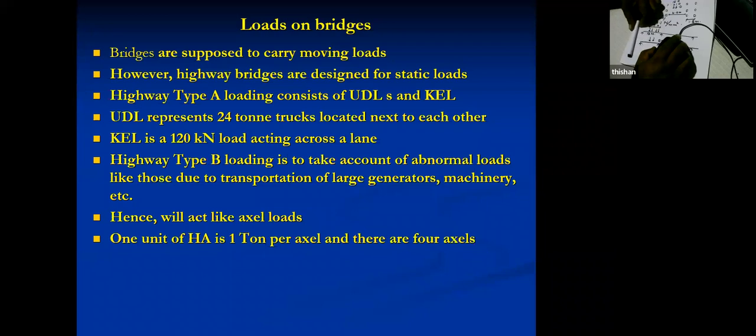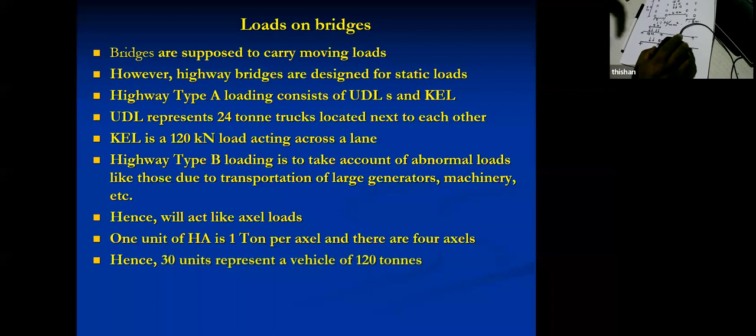And on a flatbed, we can have 600 bags of cement. One bag, so 20 bags of cement is 1 ton. So basically, 600 bags of cement means 30 tons for the truck, the load. And the truck is also heavy because it consists of a heavy engine, because it's a powerful vehicle, axles, all that. So the weight of the vehicle also can be about 6-7 tons. So if we assume the weight of the vehicle to be close to 10 tons, we are talking about a 36 to 40 ton vehicle over 10 meter length.